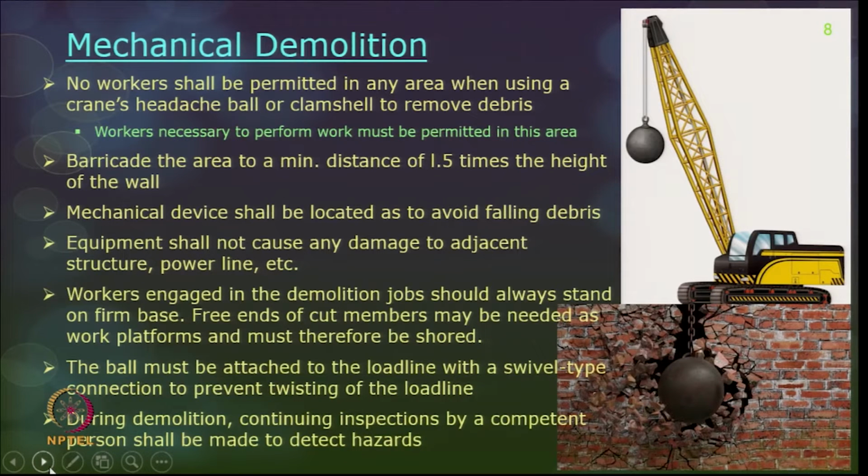And the workers engaged in the demolition job should always stand on a firm base, and the free ends of cut members can also be used as a work platform, but they must be properly shored and fastened when the workers are using it as a base to stand.